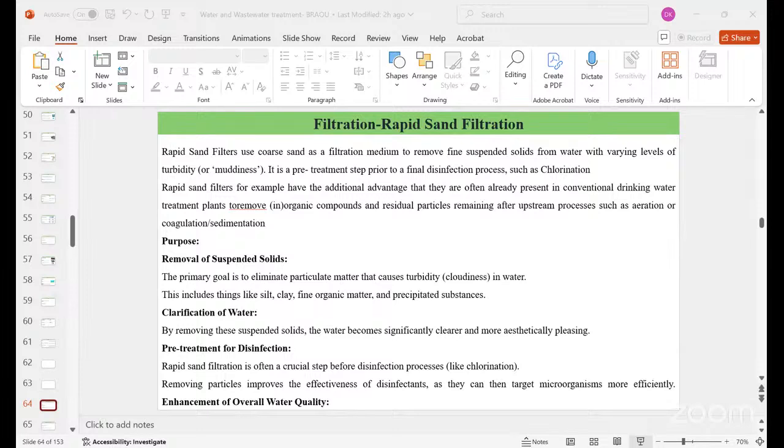It also increases as the particulates accumulate in the filter bed and reduce the pore sizes. So if there are more void spaces, more pores will be present. When there is a maximum head loss, a reduction of the pore sizes will be observed. And monitoring of the head loss is very crucial in order to perform the backwashing.